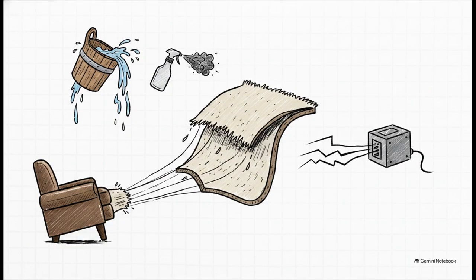So what causes this kind of catastrophic failure? Sometimes, sure, it's a manufacturing defect with a weak latex bond right out of the factory. But honestly, very often, it comes down to facility maintenance. Prolonged water damage or flooding will rot the latex over time. Chemical saturation from overwetting the carpet during cleaning, or even acidic pet urine turning alkaline, will just eat away at that backing. And get this, using ozone generators to clear out room odors can actually introduce gases that chemically dissolve carpet latex. Who knew? Also, physically dragging heavy furniture or repeatedly grinding feet on corner pivot points will just physically tear those backings apart.